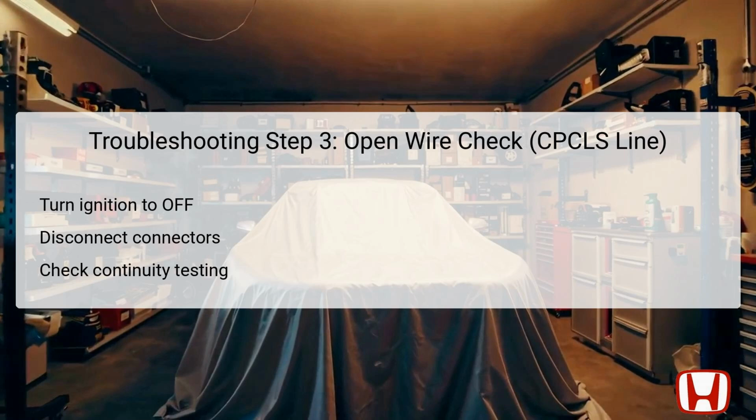With both connectors removed, check for continuity between test points 1 and 2, ensuring the solenoid wire harness is properly isolated. Test point 1 refers to the solenoid wire harness, while test point 2 corresponds to the PCM connector. If continuity is detected, this confirms that the wiring is in good condition. Thus, the TCM software might need updating or replacement. If not, investigate further to repair any detected open circuits to restore proper operation.